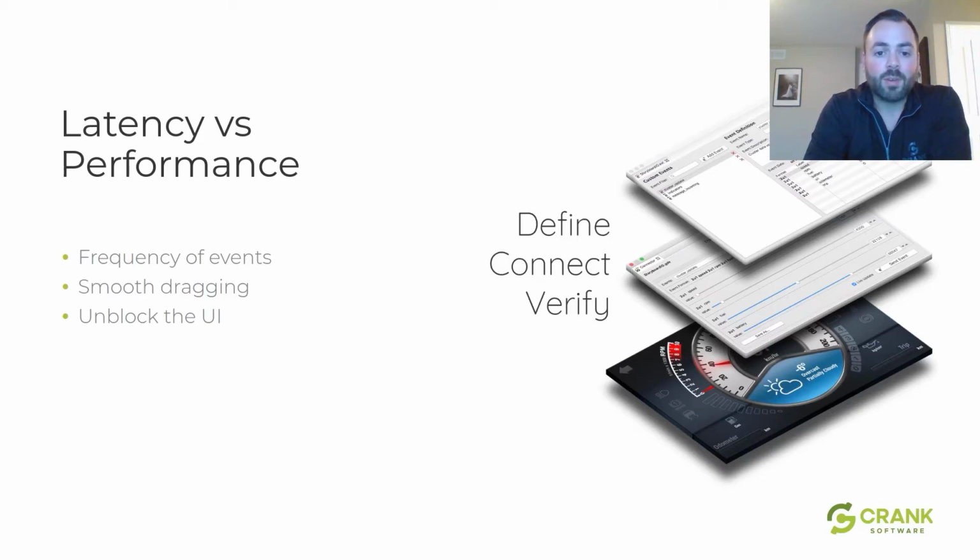So, if you're only getting a drag event every perhaps 20, 40 milliseconds, then things might look like you're stuttering and things are hopping and jumping, and it's not giving you that nice smooth transition. And so it's possible that could be something that has to do with the touch panel. Maybe it's just simply lacking the fidelity required to achieve what you're looking for, or maybe it's just lacking calibration. But again, the end result is what appears to be a poor performing user interface.